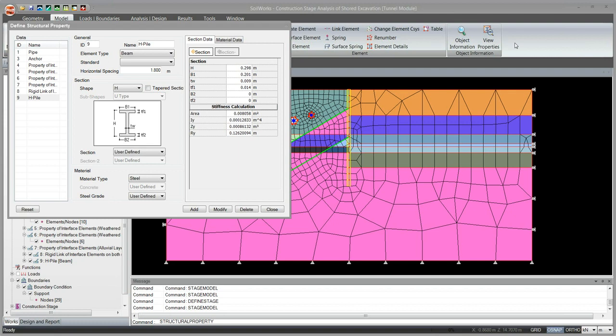Okay, so I just cross-checked in the foundation module again. If I want to apply a non-uniform section along the pile, we can define the pile section as a tapered section and then we can assign the pile as a tapered section to define the non-uniform section along the pile length. So I hope it answered your question, Mr. Montesi.